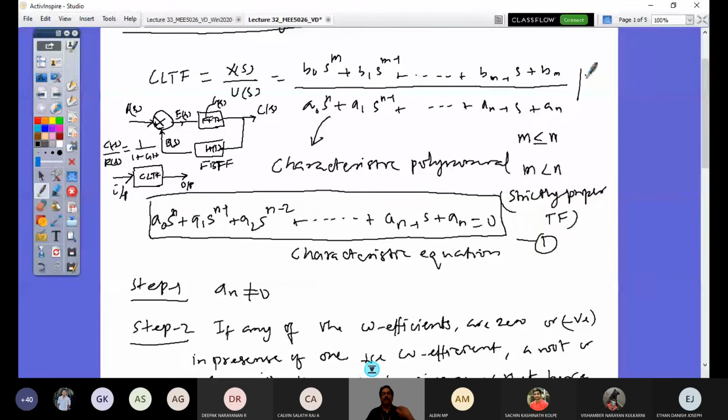This feed forward transfer function will be called an open loop transfer function when we have no feedback. That is simply that the output is not going to be dictated by the input. You give an input and get an output. That is what gives you open loop behavior. But this open loop transfer function can be corrected so that your output has a good correlation to your input. Then there would be a feedback signal, and that is where we define this output by input relation through this. And if you look at this, you should not mistakenly understand it as an open loop system.